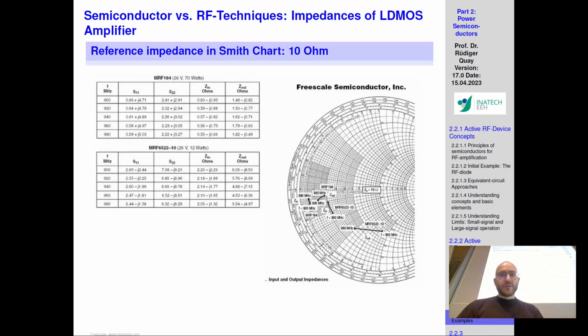As we said beforehand, at the end of the day we're trying to design a device that amplifies a signal, and that signal should reach something like your phone. Thus it comes through the base station. The base station has high power amplifiers implemented in it. The signal goes through other components of the transmission network that we'll hopefully see in this lecture as well, but they end up at the power amplifier. The power amplifier drives its power into the antenna.